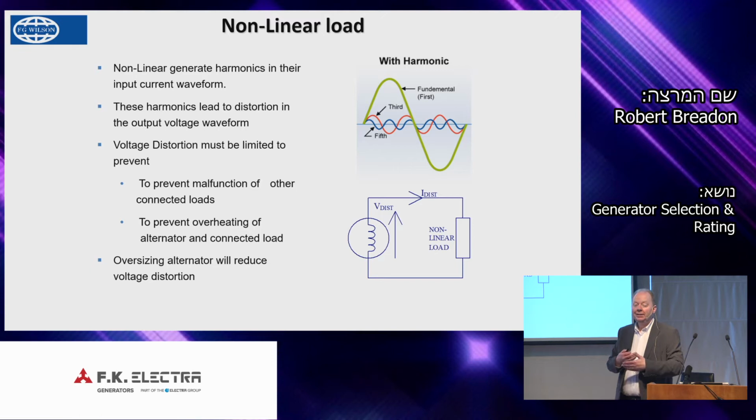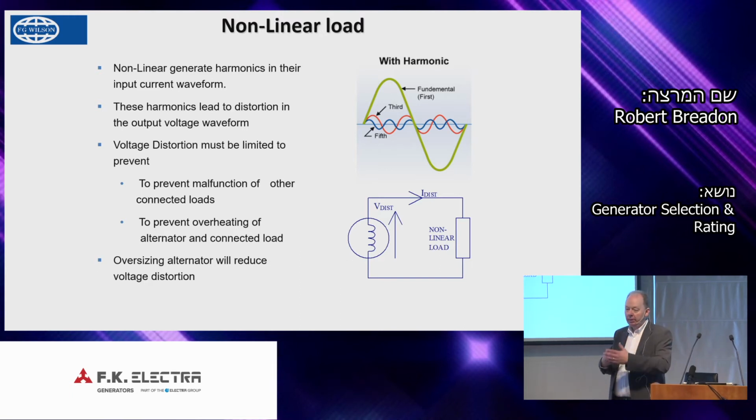It will eventually probably destroy other equipment that the generator is connected to, because the voltage waveform will become so poor that the distortion levels will be so high that there will be heat buildup maybe in some of your more sensitive connected load. And of course, it will probably damage or burn out or overheat the alternator. So we need to be careful in the selection. And again, our selection software provides that capability and will select the right alternator for the application.